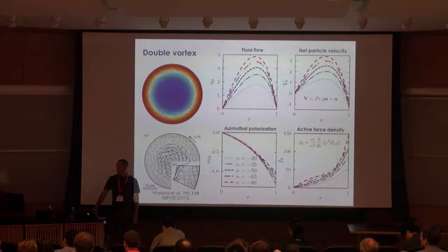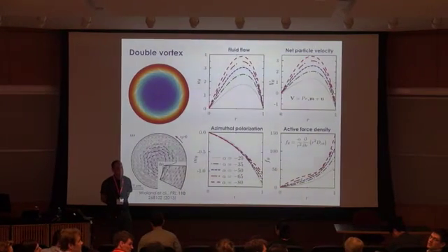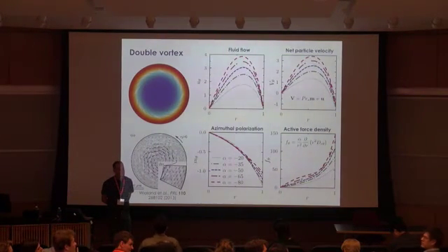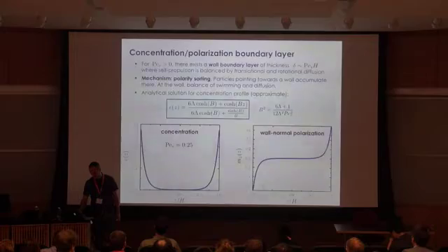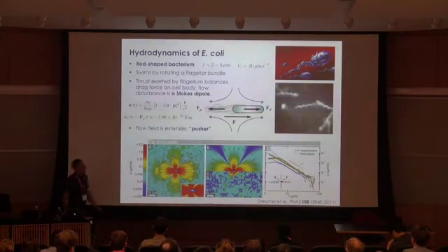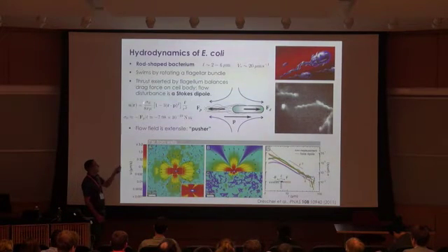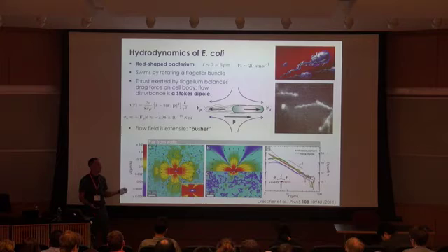If there are no more questions, that's the, oh, there is one more. Just two short questions. You showed the strength of the dipole very precisely, 7.98 times 10 to the minus 19. I was wondering what specific model produces this. So this is just a numerical fit, right? We took the flow field for a point dipole. Well, we didn't, I should say. It was done in this paper, and it was fitted to the actual flow field measured by PIV, and from this you can extract the only free parameter, which is the dipole strength.